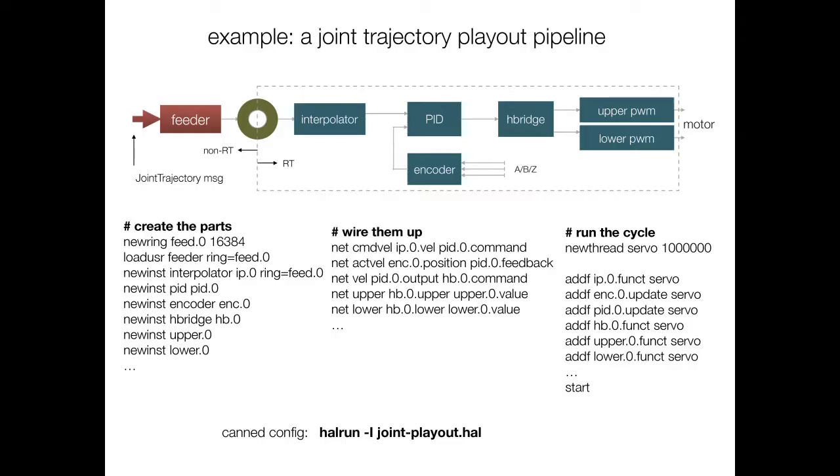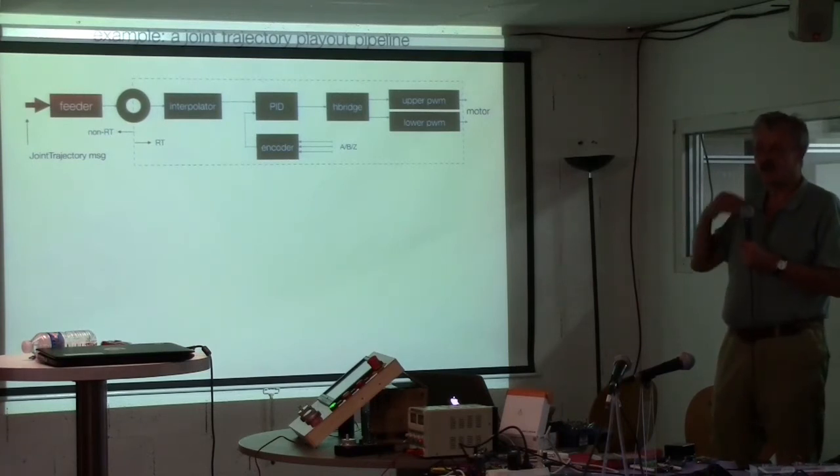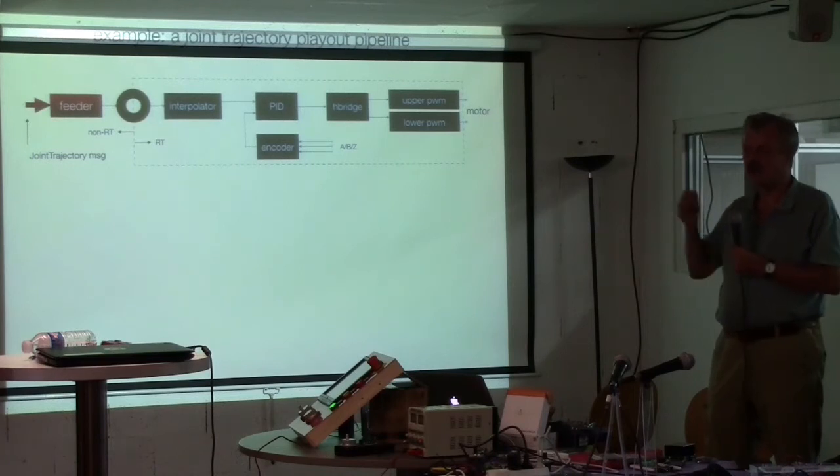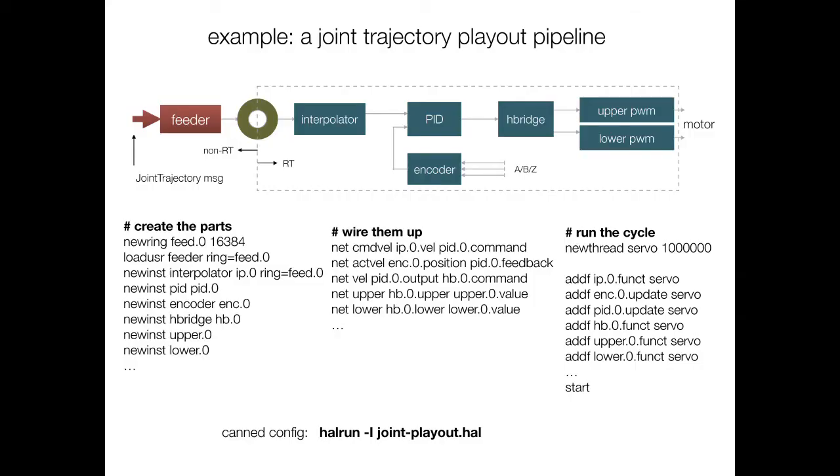So as the machine moves through a long linear move, for each cycle advance in time, you need to calculate the next position for that particular joint. And that is what an interpolator does. It takes such a segment and a point in time as an input, and it gives you the position at that time. It also does certain jobs which are good for the machine. For instance, if there are discontinuities in the curve, it smoothes them out, and that reduces the mechanical jerk and load on the machine.